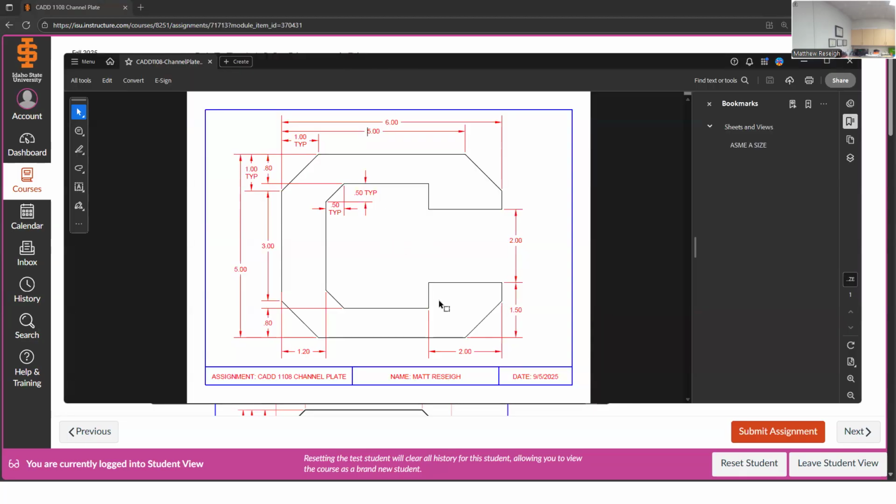But I just kind of do a quick look at how I will proceed. I kind of like to do that. You've seen me do this a few times. Something with my ASME critical eye, I'll notice that the dimension line extends, like right here, it just caught my eye. This extension line on this dimension overlaps onto the object right here. This could have been pulled back so that I don't overlap extension lines over the top of visible lines. So that's just something I've noticed, a little revision on this drawing. Real small detail, and of course we're not dimensioning, so it won't be a problem, but it just caught my eye.